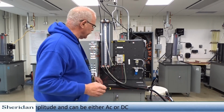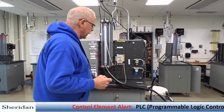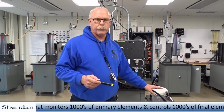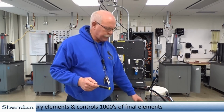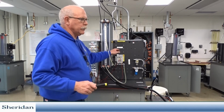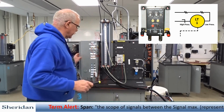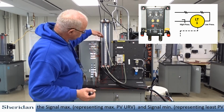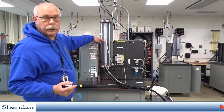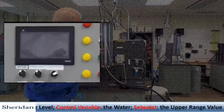It's coming from our transmitter going to our controller that reports this level, and our controller is set up so it will provide a proportional output to our final element. Final element in this case is the motor and pump combination. Our primary element is an integral part of this transmitter. The transmitter is a pressure transmitter and it's going to the PLC. Now as you can see here, you have the water level. We have a set point and it is maintaining that water level and it can be changed. So I'm going to change it through the control and bring it down just a little bit.